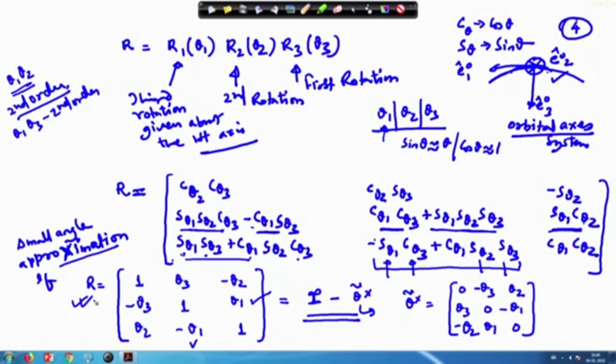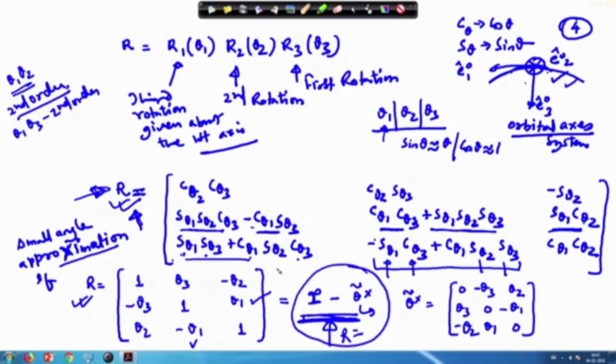So, what is the benefit? If the angle of rotation is small, if your satellite is here and the deviation of the body reference frame from this orbital reference frame is small, in that case that rotation can be approximated like this. Okay. You do not have to take the whole matrix and then work it out. So, this is the simplification. Now, the other part is that you do not have to memorize this matrix R. If you have to take larger angles, only then there is a problem that this matrix needs to be computed anyway. It is better not to memorize it, but rather compute it from time to time whenever it is required. Okay. When the angles are small, it is very easy to remember, just use this R equal to this quantity. Okay. So, this gives you the resultant matrix, and now you can go back and do the job you want.